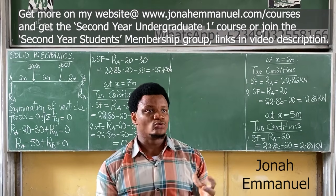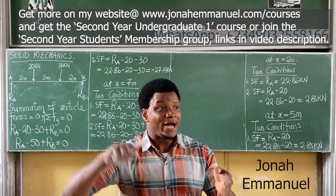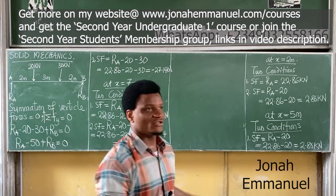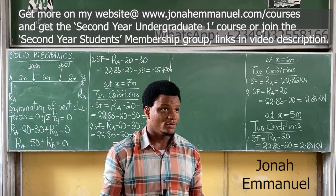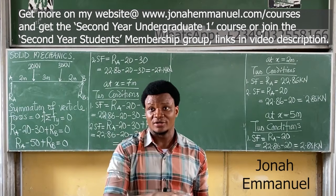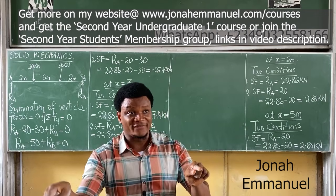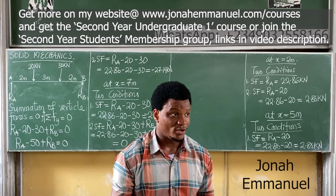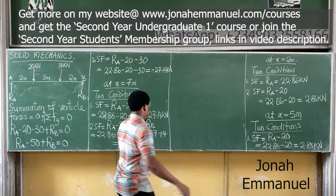In higher examples, it might not give you exactly zero. It might give something like 0.000012. That's the zero, because you're using what there? Approximation. Or we can have something like minus 0.015. It's still zero, just due to approximation. But for now, always observe that your shear force will give you zero.